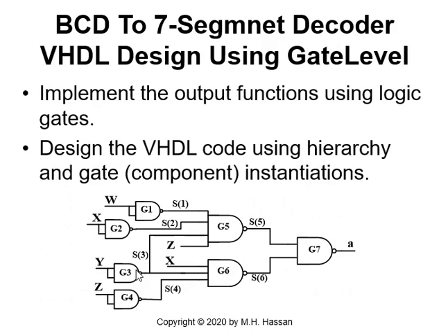Now, we can also generate a gate level design. This is slightly more complicated and very useful, because if we do a counter with delays, we can add delay elements to compensate for the delay. When you design on the gate level, the design can be in all NAND gates, as you can see here. So this is the hardware implementation for A, using all NAND gates.